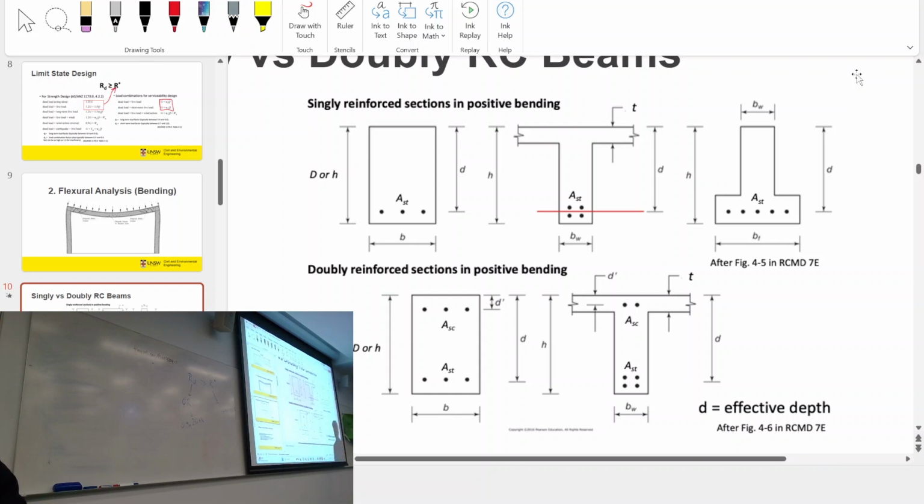So all the formulas, they'll give you all the formulas, so it doesn't matter anyway. But if you remember from 2400, when you have composite sections, do you remember transformed sections, where you make the area seem bigger for different materials. So like this, steel, right? It's got a larger yield stress. So you can essentially have the equivalent of this in concrete would be a lot more area, if that makes sense. But yeah, they have all the formulas, and you just go through them.